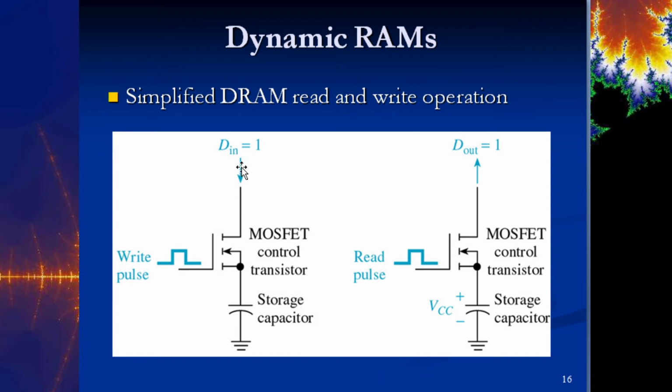So once that happens, the D1 will have VCC on it, or a high. Sometimes it's 5 volts, could be 3.3 volts, but whatever it is, it's a high. When this write pulse hits the gate, it shorts the drain to the source, and we get current flow, and it will charge the capacitor. And that voltage, whatever that voltage is here, gets put on this capacitor. So the DRAM circuitry has to provide that write pulse when this is ready.